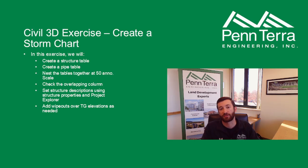So, last exercise we're going to do today is creating a storm chart. We're going to create our tables, the two tables, and nest them together. We're going to check to make sure everything's drawn in the correct direction. And then we're going to set some structure descriptions using the structure properties and the Project Explorer. And I'll show you how to add some wipeouts over the top of grade elevations on structures that don't actually have top of grades, like outfall pipes, end walls, head walls, those types of things. So that's where we're headed.